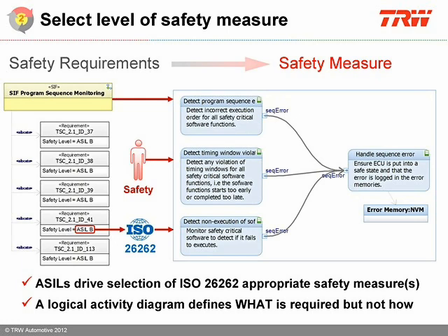For example, a SIF might indicate that a windowed watchdog with a separate time base is required, but the SIF would not state that a power supply with a built-in watchdog should be used.